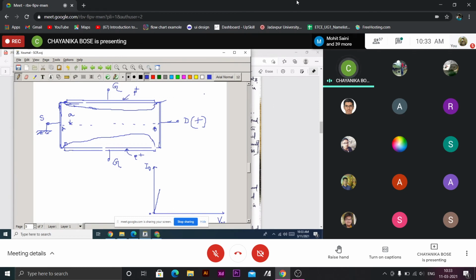So the resistance of this channel RAB now will increase as the area is smaller here. That means as VD increases, the resistance itself increases. Resistance is not now a constant, a proportionality constant, as in the case of Ohm's law, a linear property.